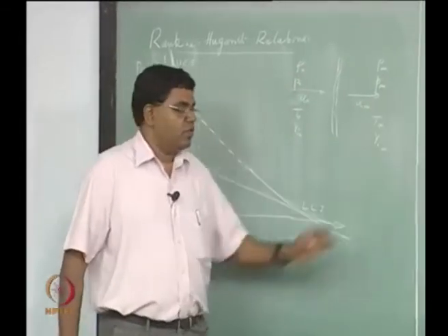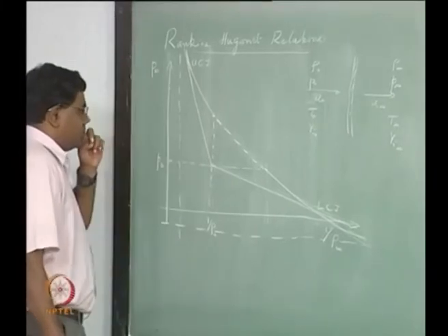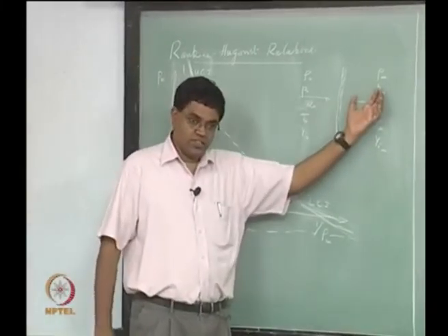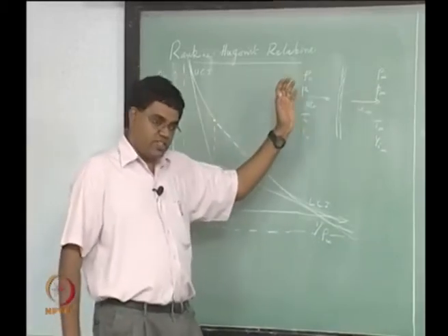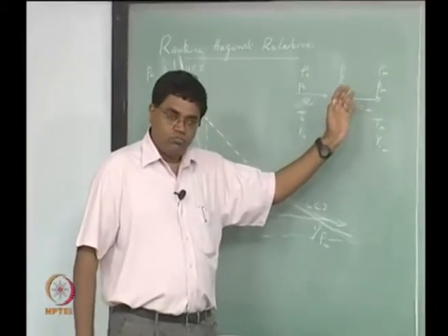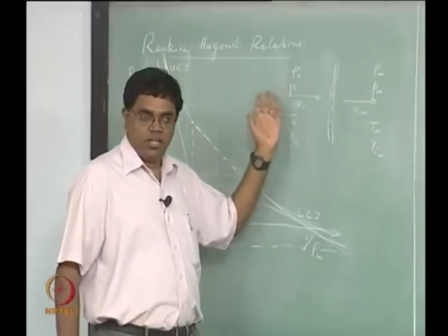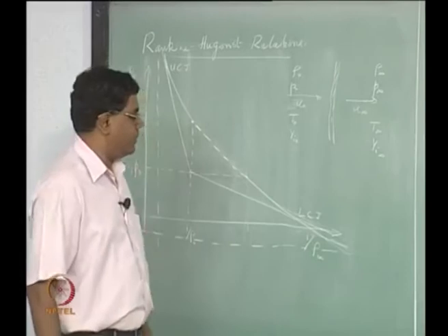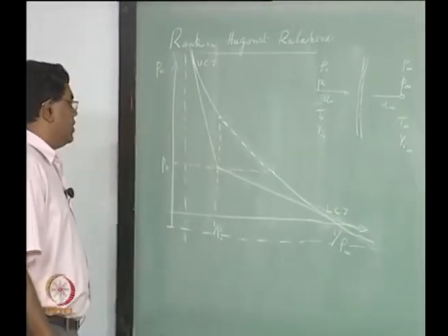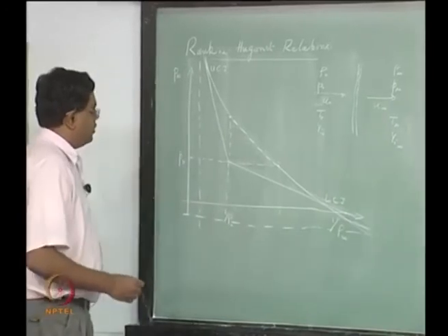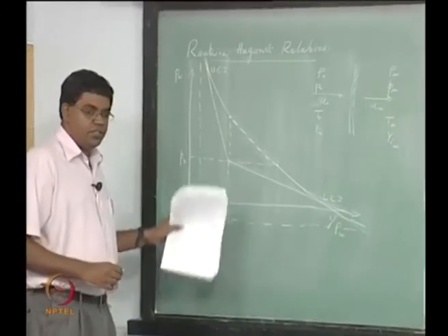Okay, so the answer there is they could decelerate all the way down to subsonic conditions, or they could get decelerated to supersonic conditions that are still slower than the incoming supersonic speed. This is typically what you're expecting when you're now looking for a detonation wave that is not a Cj detonation.